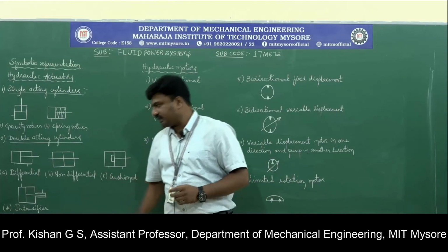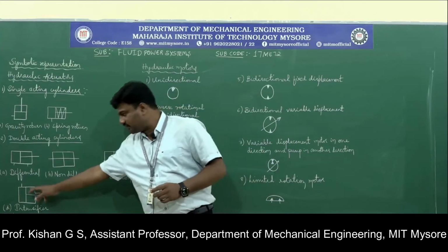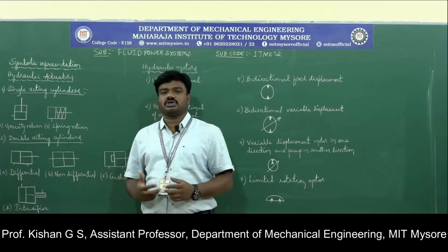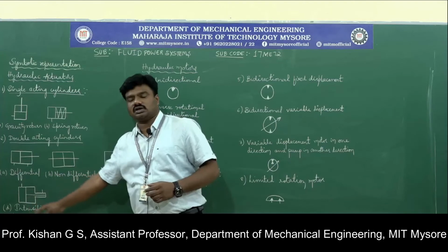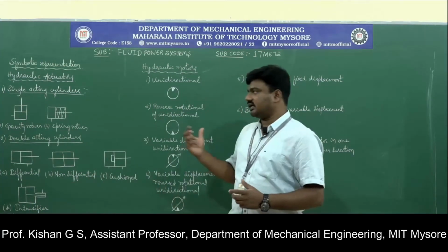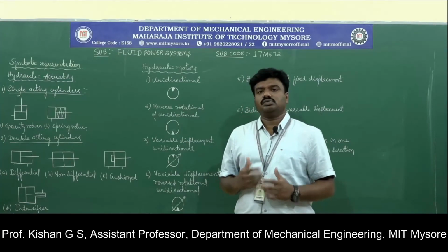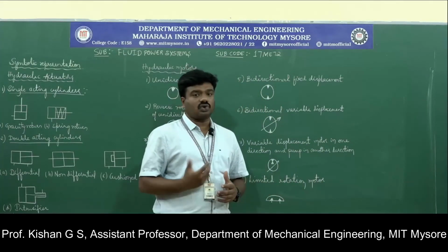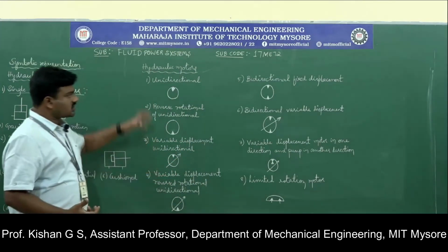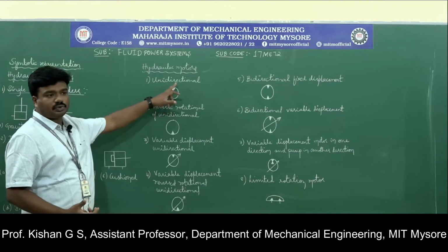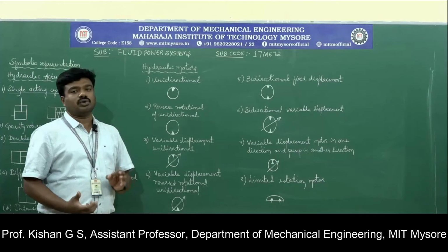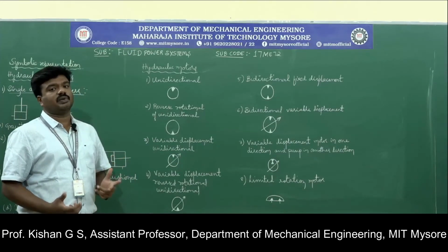And one more type, pressure intensifier, that consists of piston and piston rod end, and which results in an increase in the pressure of the fluid, and this is the symbolic representation for pressure intensifier or intensifier for double acting type of actuator. Moving on with the hydraulic motors or the rotary actuators, we have different categorizations to represent here. Keep in mind, a triangular portion with a shaded representation represents the hydraulic motor. If it is empty, it is taken to be pneumatic.